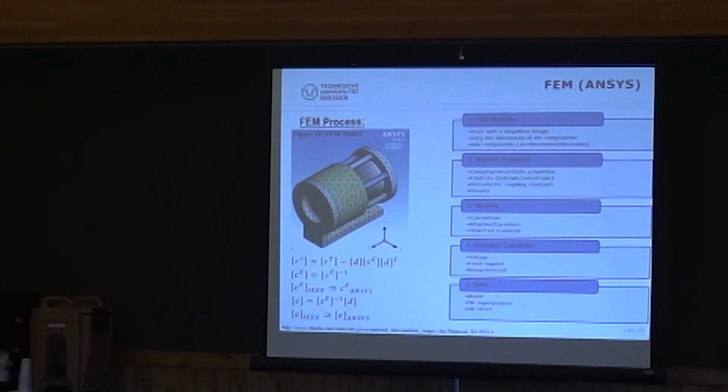Of course, I have to take a simpler model so that I don't have problems with contact interface and other details like the head of the screws and so on. And I have to implement also all the piezoelectric properties according to the ANSYS format that requires a lot of juggling around.